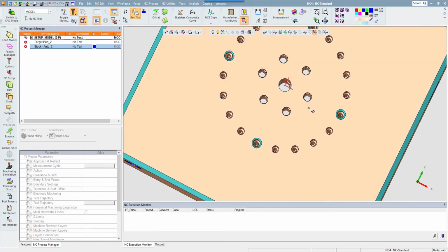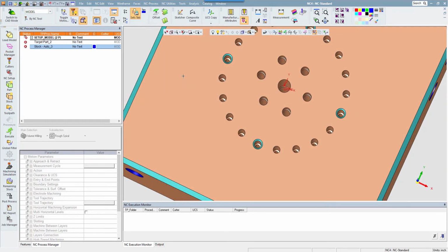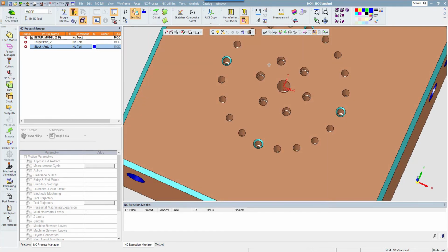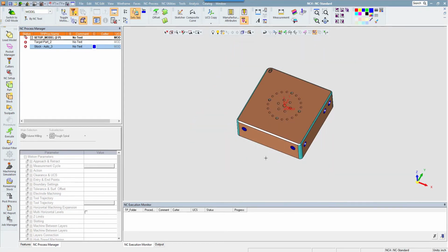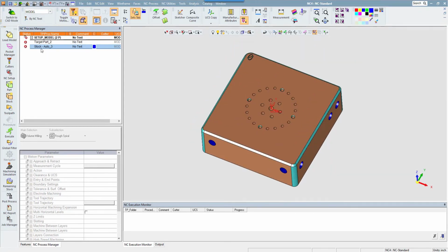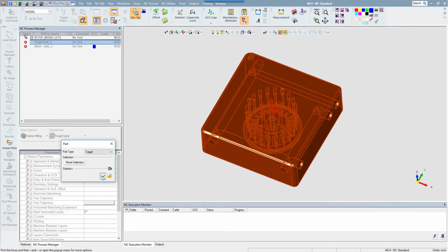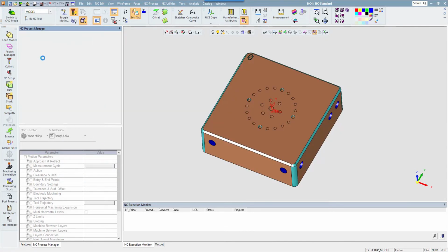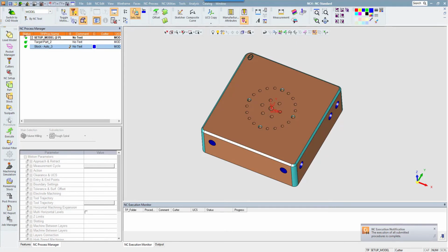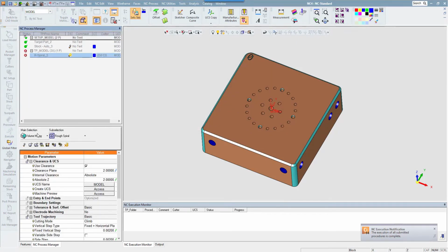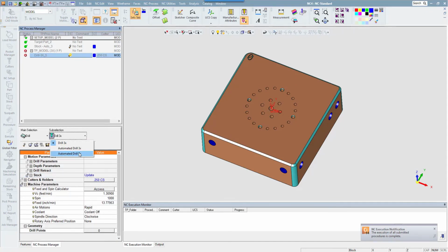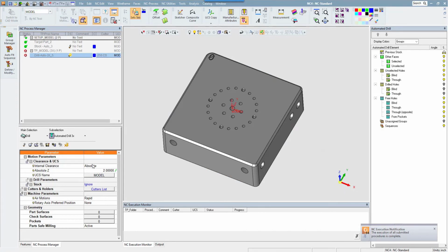Okay, so we can see there's more pins than there were before, and these are slightly different back drill depths than what we had before. The designer made some changes here, so we're just going to go ahead and get this set up. Go here, here, get our tool path, get our procedure. Sorry, drill, auto drill. And again, this would all be templated and grabbed by criteria. We wouldn't usually sit here and pick through this.